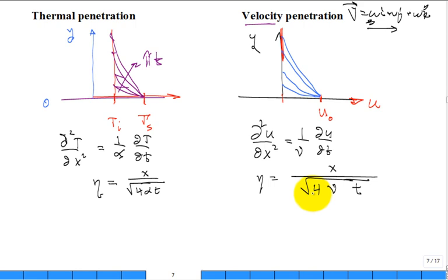And so now you can say, I know the profile, and we know the error function, and so now I can say, how far out, this is classic fluids, how far out is this penetration of my velocity profile felt into that fluid far away from this plate? Normally we have a plate and we would flow the fluid over it, and then we talk about the growth of the boundary layer. Well, here it's impulsively started, and I have a growth of something, a penetration depth, like a boundary layer into it.